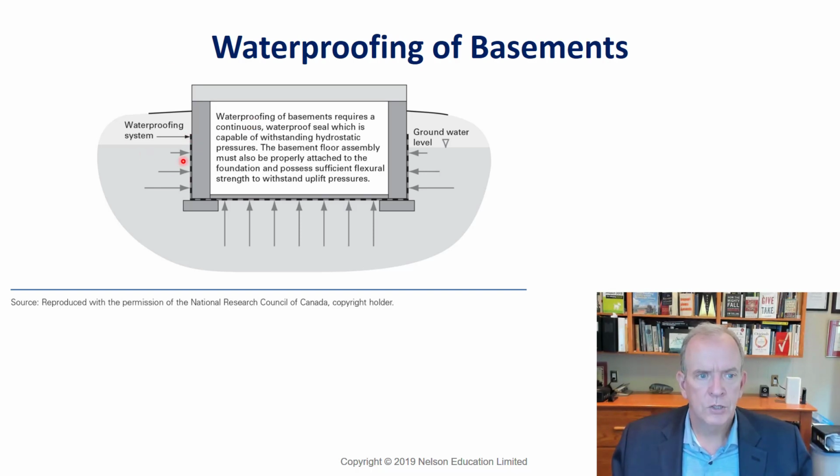And so it can actually put pressure on your walls, on your floors, and waterproofing has to have methods to seal this, but it also has to have methods to reduce the pressure, particularly upward pressure that comes from up above. But with new walls that are formed, when you do the foundation walls, you have to make sure that you put temporary bracing on long walls, because if you don't, when you backfill that, and say it's pouring rain and the backfill is very wet, then there's a lot of hydrostatic pressure against the walls.